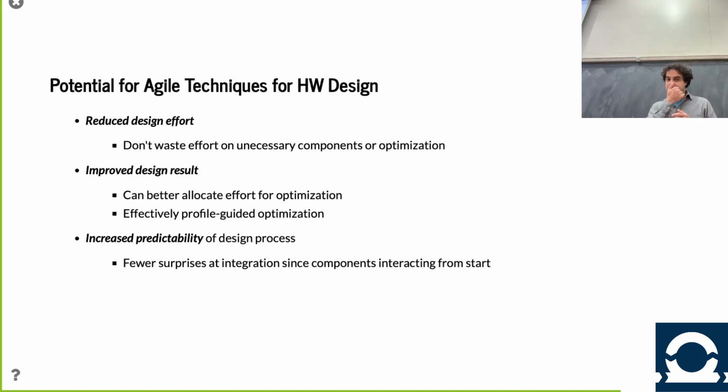One of the things that's really painful is, let's say you have this late integration of your design and you're way off your target for performance. That's really rough, right? There's only so much you can do at that point. You've already written all this RTL, you've already verified a lot of it, and now you need a massive change to your architecture in order to reach the performance target you want. That is a disaster, right? You're going to do everything you can to model and plan to prevent that from happening, but if that does happen, you're in a bad place.